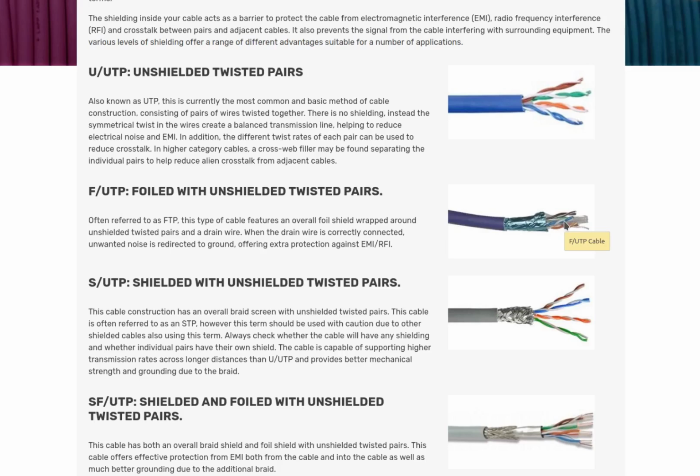So if you look at the grey cables connecting the USB to Ethernet adapters to the switch and compare their flexibility to the red, yellow and blue cables connecting the Pis to the router, you'll see those grey cables are a lot more rigid, as they are Cat6 cables with this internal plastic former, whereas the red, yellow and blue cables are Cat5 cables and they don't have this internal former, so they're a lot more flexible. And that's something to remember if you're trying to run some wiring. Cat6 cable is a little bit more stubborn to go round corners.